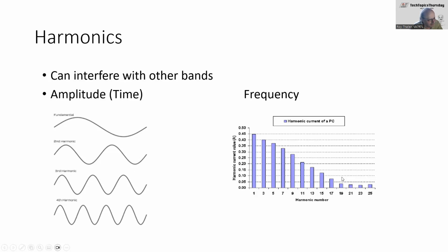you'll see something like this where you'll have your primary fundamental frequency, and then you have your various harmonics, and these will decrease in size, but these can go out quite a long range if you haven't designed things properly electronically, especially if you're using an amplifier without a low-pass filter. You can get harmonics all the way out here. You could be transmitting in the HF, but you can be having harmonics up in the VHF and UHF.